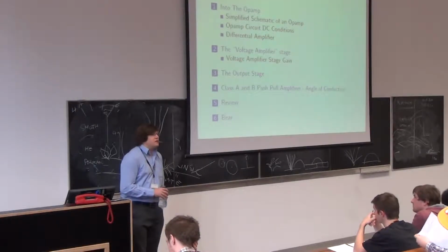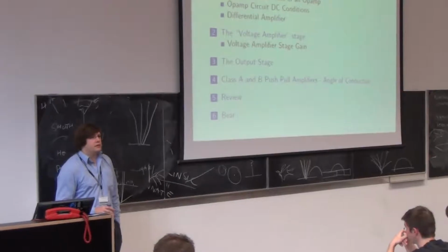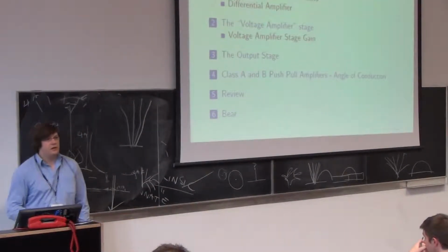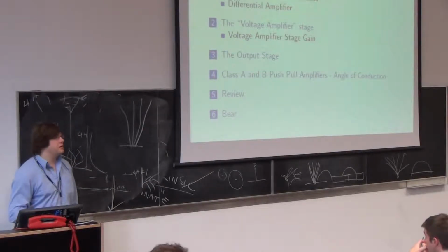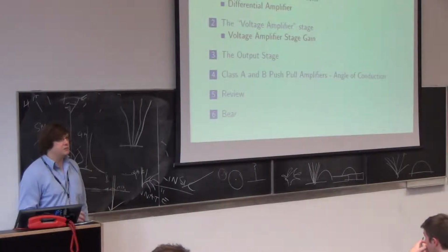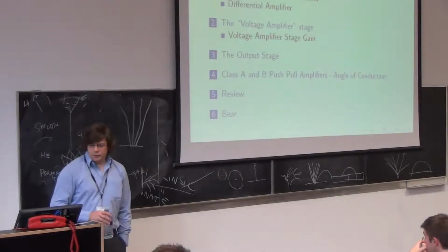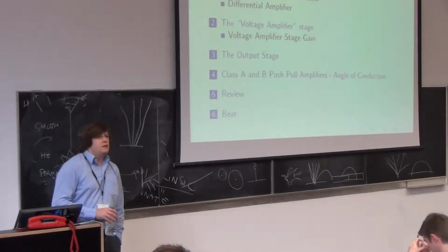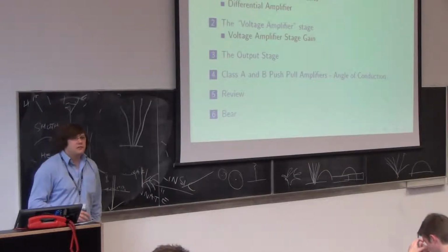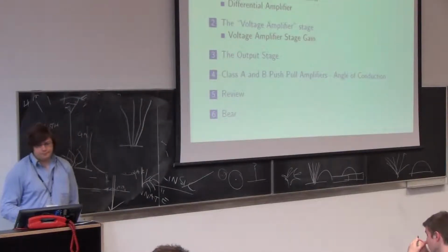It is not, in fact, responsible for all of the voltage amplification, but the majority. People tend to gloss over the fact that the differential amplifier has a gain as well, a voltage gain which may be bigger than 1. And then we'll look at the output stage, and then we'll talk a bit about amplifier classes and angle of conduction, that sort of thing.